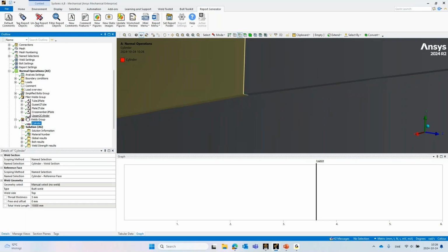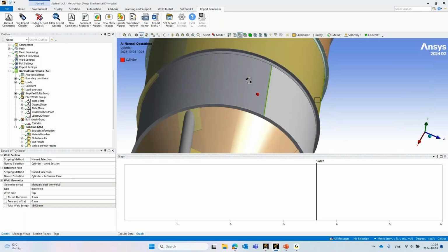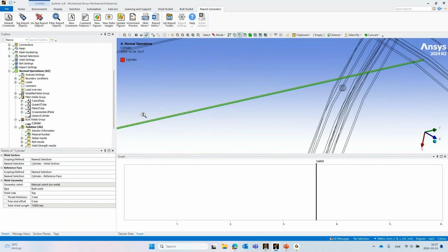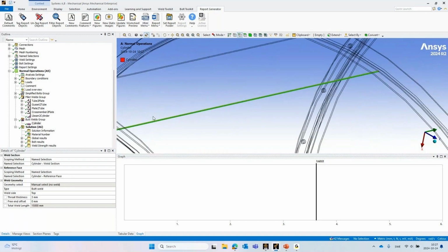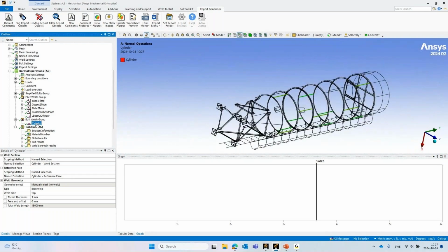And in a similar way, you can do butt welds, and they are simply visualized based on the reference face and down through the thickness. So we can see that the size matches the geometry. Talking about butt welds here, here is the standard single-sided, but now we also have double-sided and double-sided intermittent. So then you simply define the size of one part of the welding, so from each side.